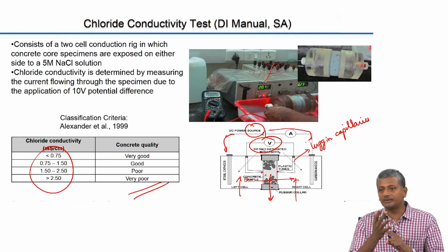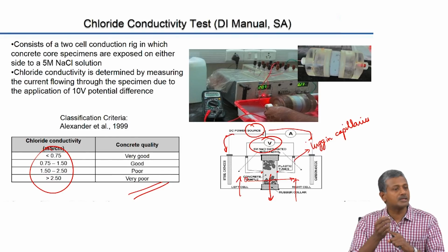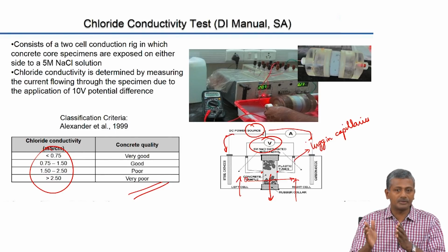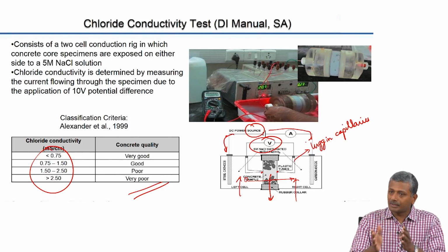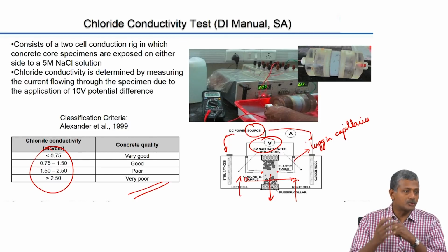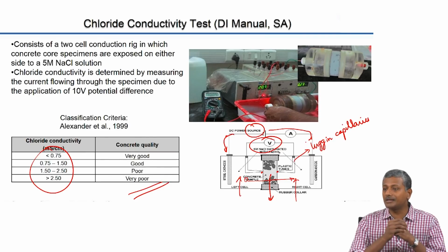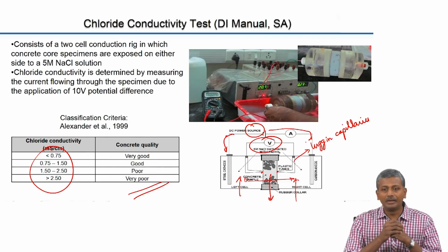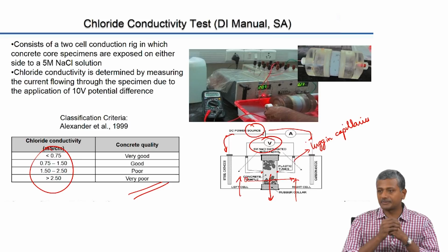In all three methods the concrete has to satisfy certain minimum characteristics. So, what they are doing is using these durability parameters to tightly control the quality of concrete that is being achieved in their projects. The roads agency has been implementing this for more than 10 years now, and they have had very good success with it.